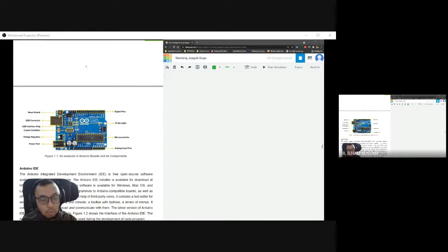So if you want to build a robot, typically this won't be sufficient because the digital pins it has aren't that many. If you take out PWM, serial communication and interrupt pins, you will only have 3 pins available to connect to a sensor or motor output. So you can't do much. And it can only support a certain range. If I'm not mistaken, it can only supply 1 milliamp of current in total.